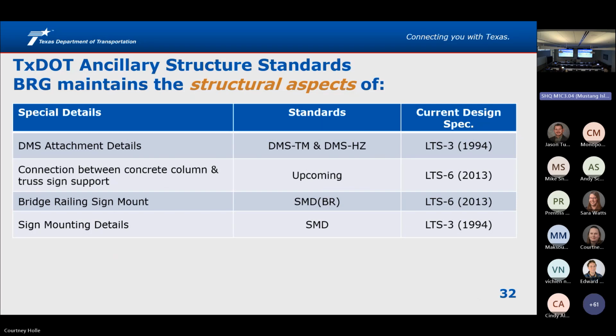Some of the other details that we are responsible for are the DMS attachments and the connection between the concrete column and the truss support. That is on the last round of review before it gets pushed through the formal review cycle to all the different divisions internally and then externally for the 95% review.